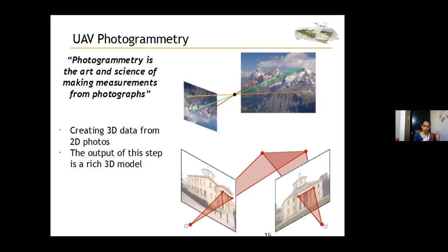Multiple observations from different directions allow for estimating the 3D location of a point via triangulation. Triangulation is the basic photogrammetric principle used to reconstruct a 3D object, where an intersecting bundle of rays in space is used to estimate the location of a point in 3D.